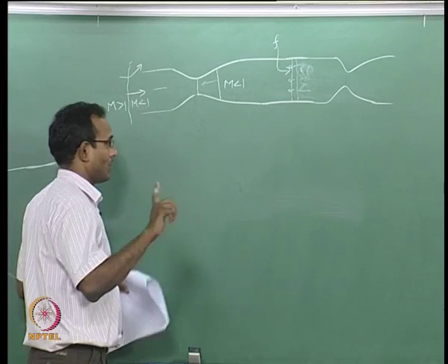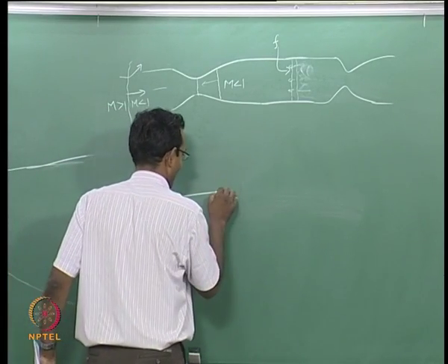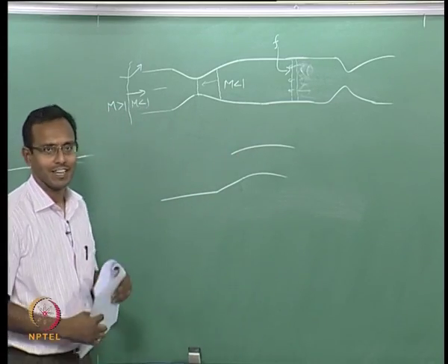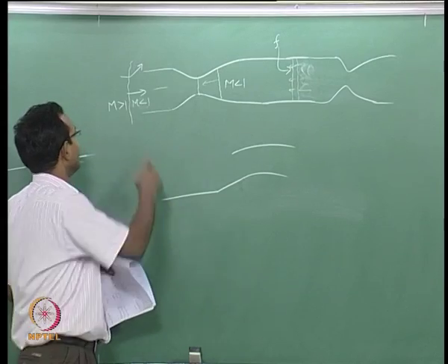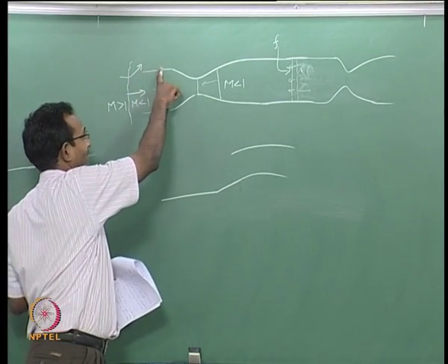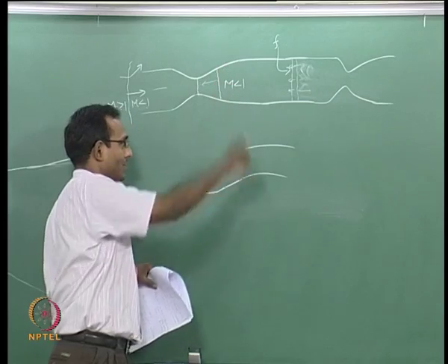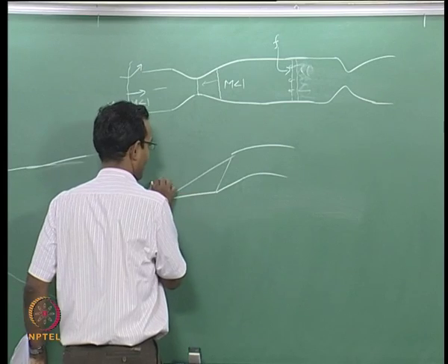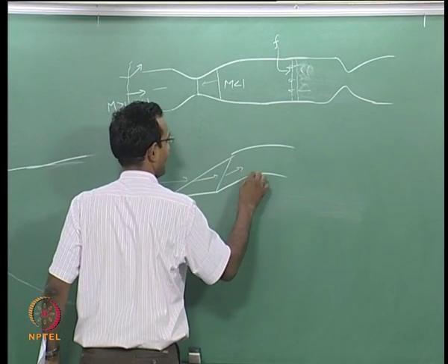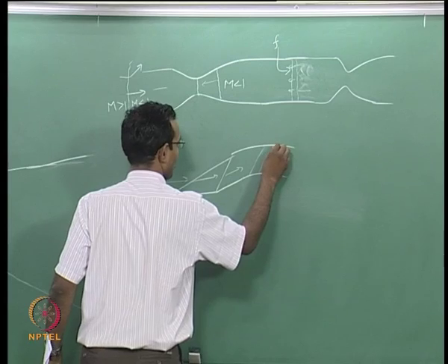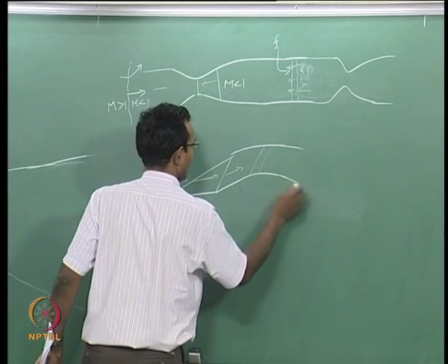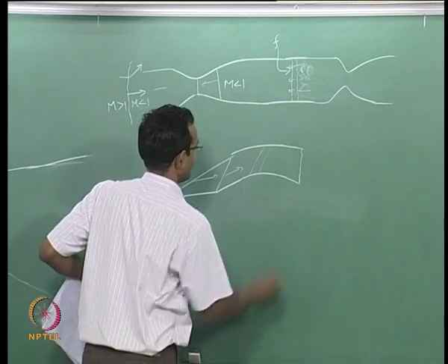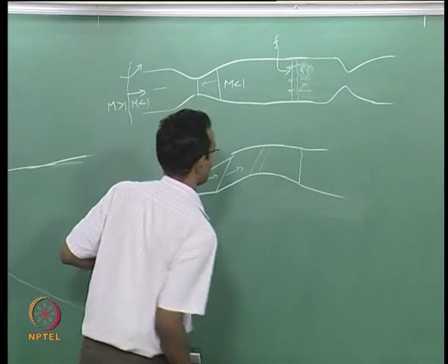And one more problem I just wanted to introduce because I am working on it. If I have an external compression intake, again a ramjet problem, typically instead of having this kind of supersonic flow incoming on that nozzle, they can have a situation where there are oblique shocks which are decreasing the Mach number slowly, and then it goes through a situation where the area decreases and increases slightly and sits with a normal shock, and then your combustor starts there.